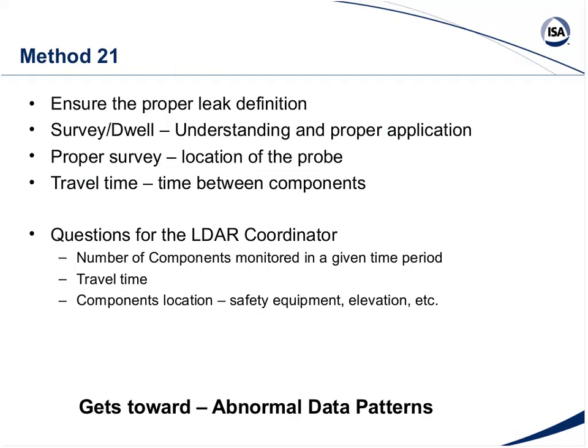When I start to do my database forensics, I can go in at the end of the day and pull somebody's route, and I populate it by timestamp. So you sort it by timestamp, not necessarily by component number. You want to look for any abnormal data pattern. You want to look for the fact that my person monitored at tank 151 at 9:55 and 34 seconds, and then was over 3 tanks down 2 minutes later. You're going to raise a red flag saying that doesn't seem reasonable.